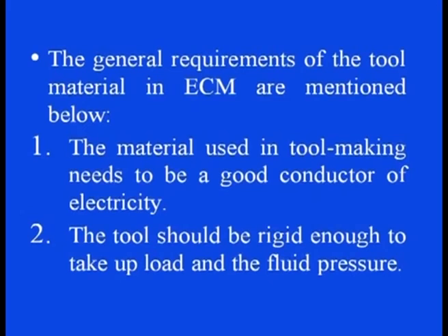The general requirements of the tool material in ECM are like this. Number 1, the material used in tool making needs to be a good conductor of electricity. Number 2, the tool should be rigid enough to take up load and the fluid pressure.